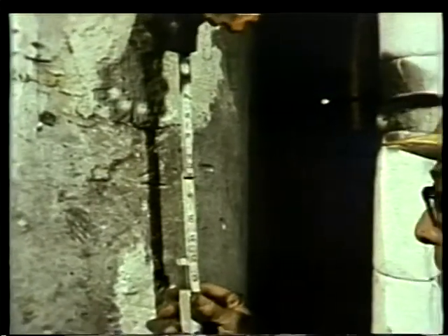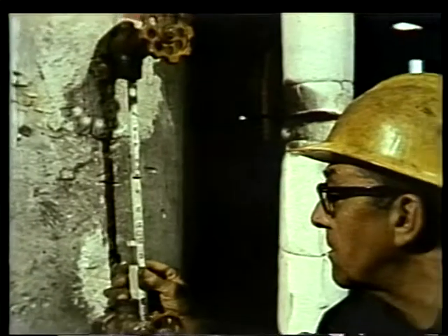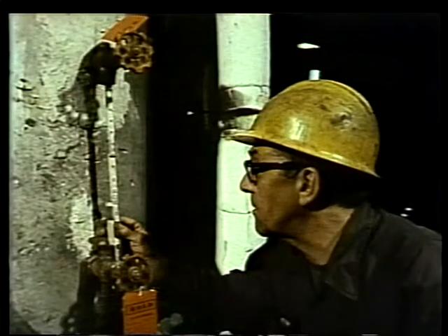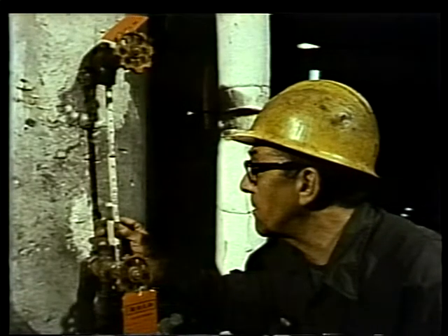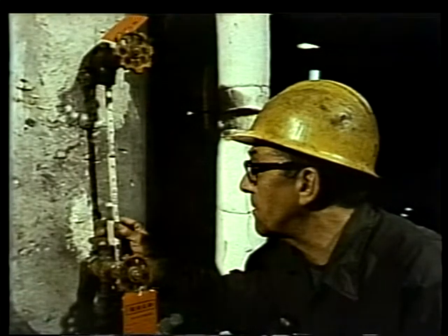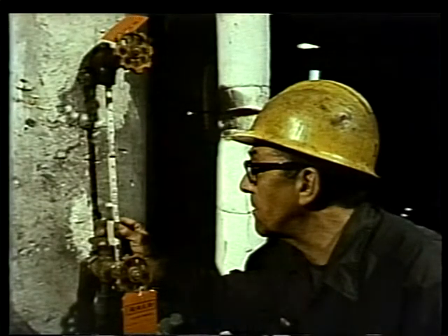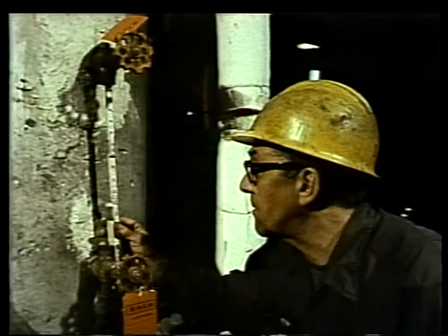Tubular glass comes in standard lengths and may have to be cut to fit a particular gauge. If the glass must be cut to size, accurately measure the space that the tube must fit into. With this type of gauge, the glass will have to be cut so that it's about 1/8 of an inch or 3 millimeters shorter than this distance. This will allow the glass to fit into the available space.